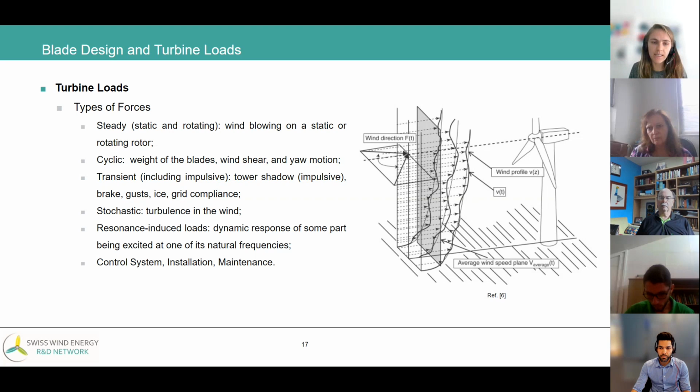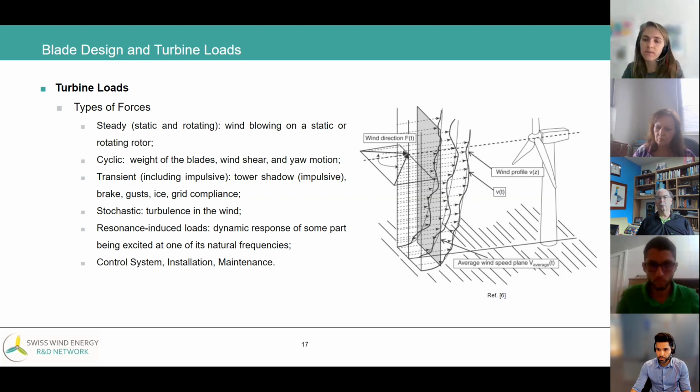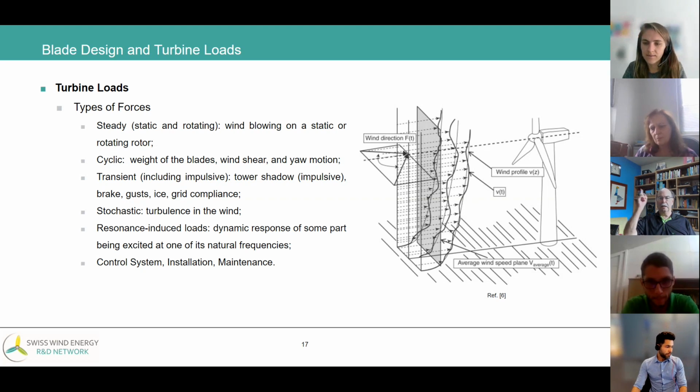Once you manufacture your blades, you take three similar ones: you weigh your blades and take the most similar ones to make the three that will go on a specific turbine, to be sure that they are balanced. If you need correction, there will be small corrections, not huge ones like with ceiling ventilators that you buy and that work like this, very annoying.